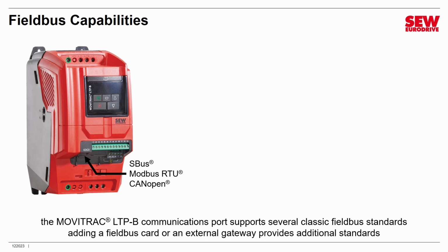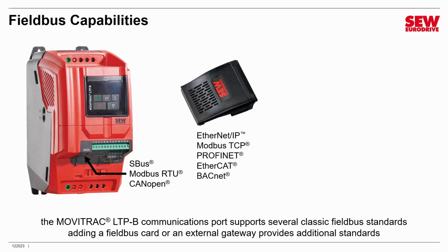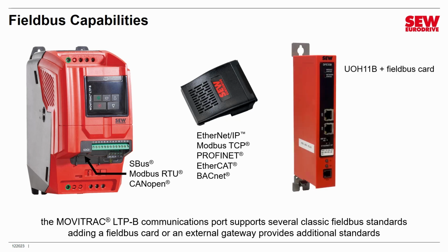However, if you wish to use more modern field bus standards based on Ethernet, you can add a field bus card to the MOVITRAC LTP-B, or you can use an external gateway, which will give you the ability to communicate in that way. If you add a field bus card, and you can see one right here, it plugs into the slot right underneath the communications port, and these are the standards currently available: Ethernet IP, Modbus TCP, Profinet, EtherCAT, and BACnet.